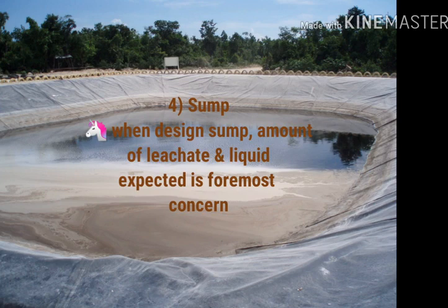Areas in which rainfall is higher than average typically have larger sumps. A further criterion for sump planning is accounting for the pump capacity. The relationship of pump capacity and sump size is inverse. If the pump capacity is low, the volume of the sump should be larger than average.